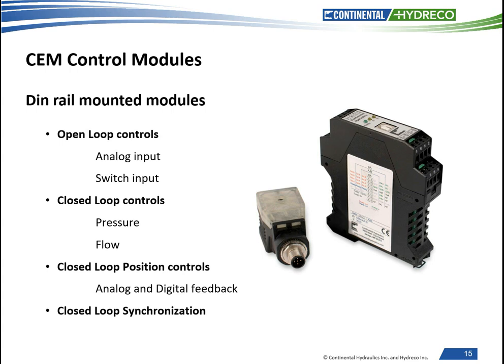There are some added features here as well. We have added filters to improve the dampening rates and allow for higher loop gains required by the high-speed applications, especially if you're going to be using the new K or X series valves. There is drift compensation for highly accurate positioning, which allows fine-tuning near the 0 when the typical high loop gains would cause instability.